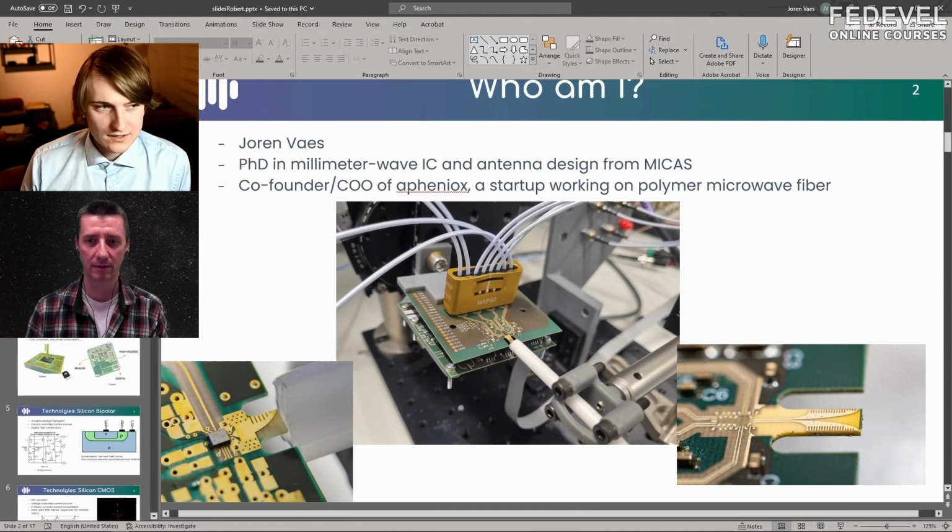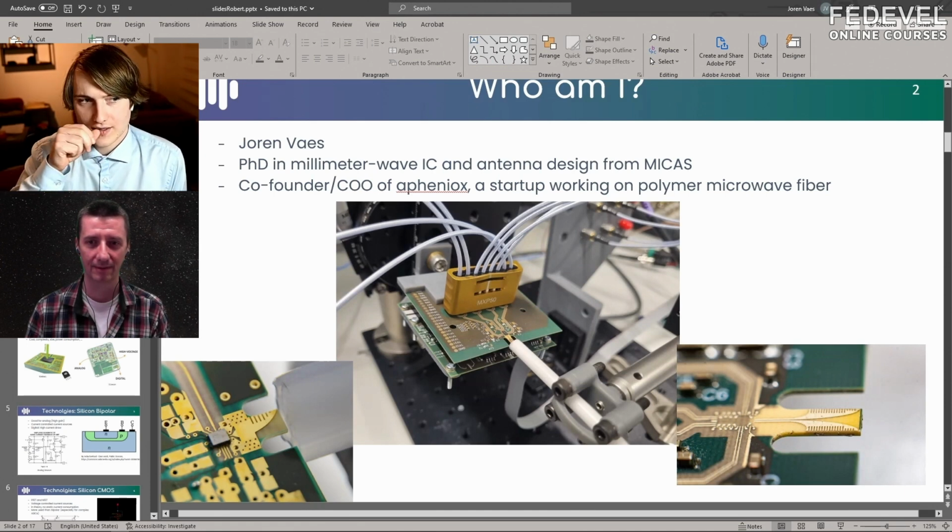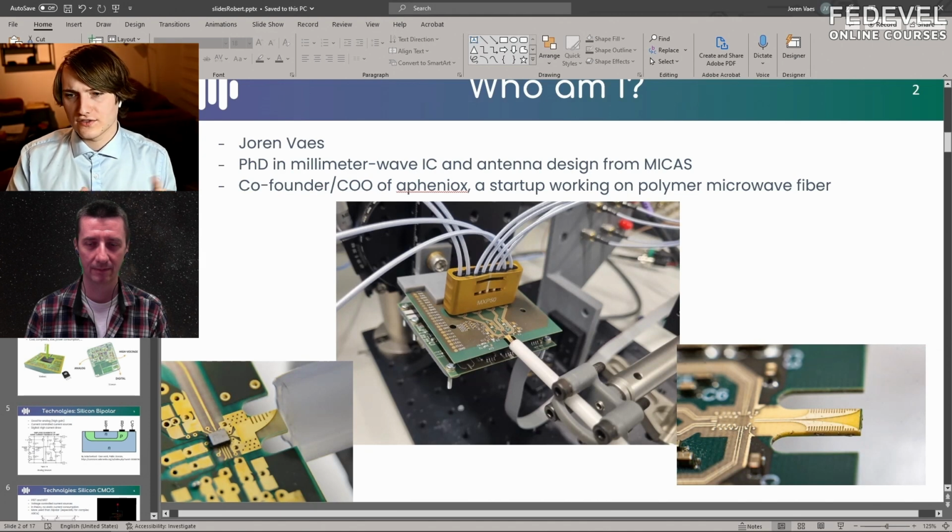Yes. So diodes is one way that they do it. It's the old way, I think. The usual way that you do it now is with SCRs, or transistors that will switch on if the voltage gets too high and then short the supply rails together. That's another way that they do it.